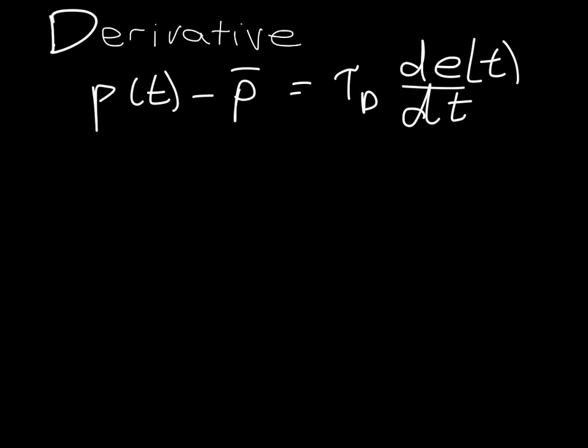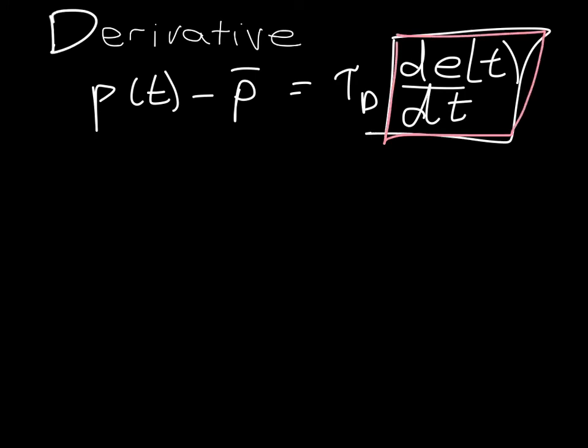The first one is that in reality we cannot build this unit. So in formal terms, a pure derivative unit is physically unrealizable, and so many times a derivative unit will make control appear significantly better than it really can be, because we cannot build this unit.